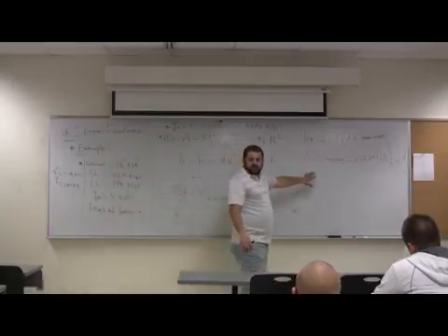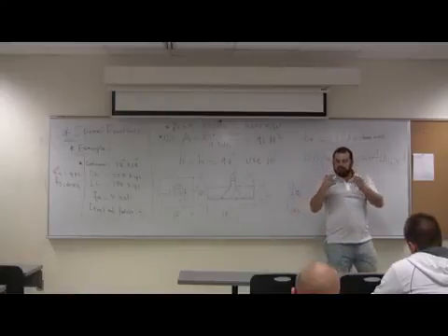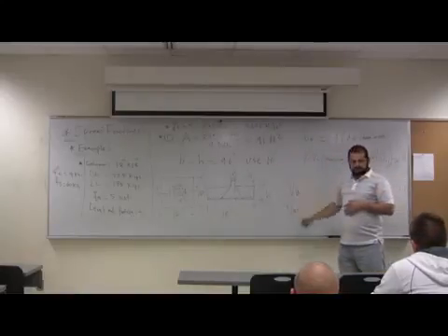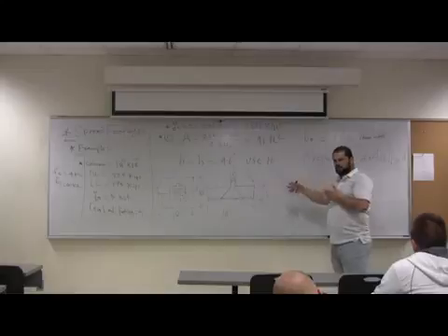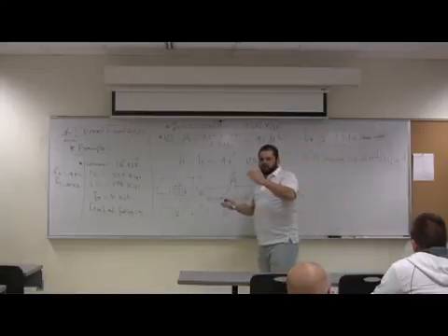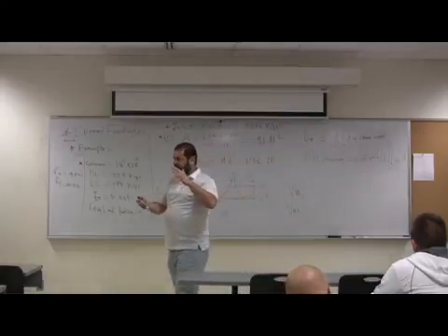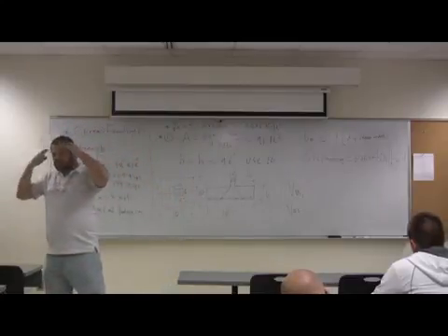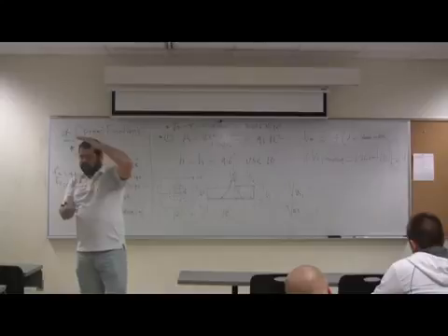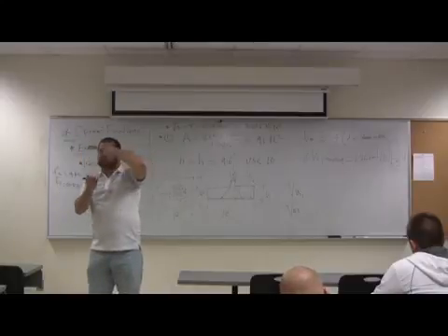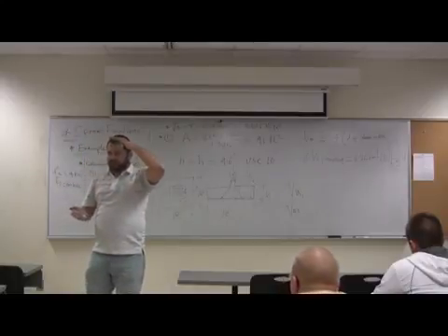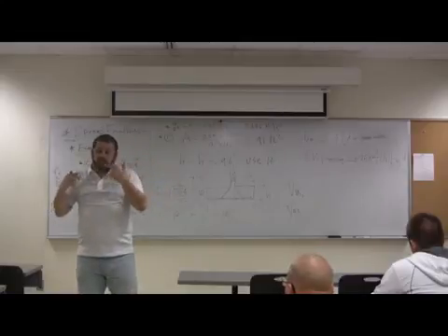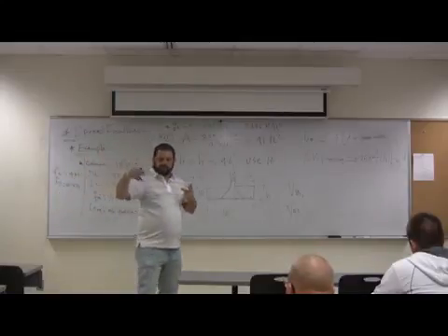Good? So this is what we need to calculate. As I told you, in the design of the footing, you need to assume D. In your mind, you will say, you know what? It's not going to be more than 2 feet, maybe 2.5 feet, 3 feet deep footing, that's deep. So you may start with like 2 feet depth and check. If you have h equal 2 feet, which is 24 inches, right? Now, how much do you subtract to get D? Check with it, guys.